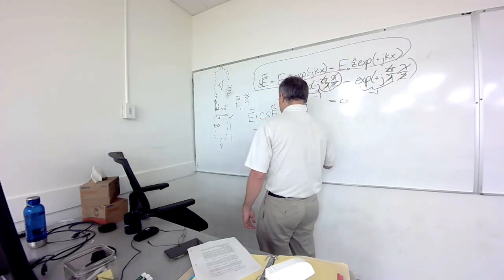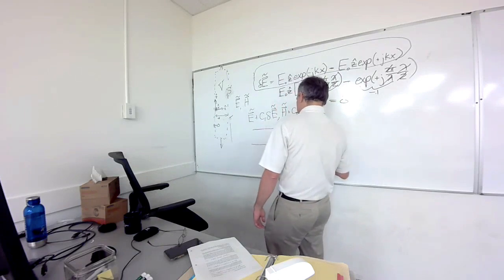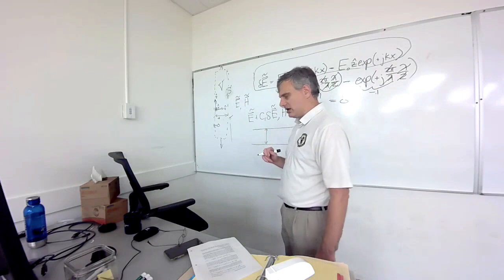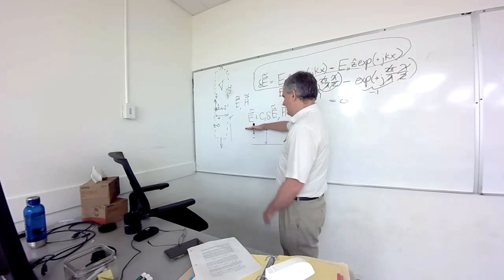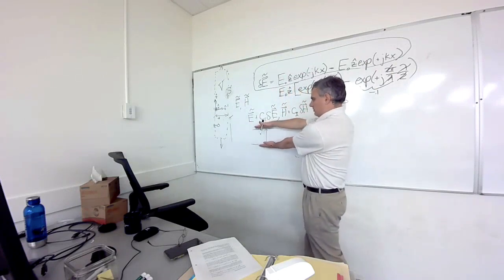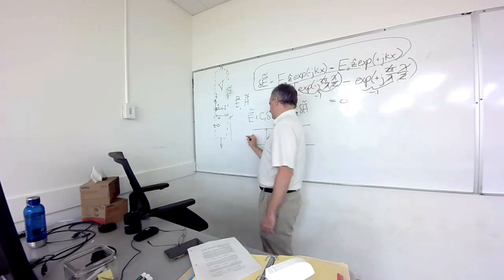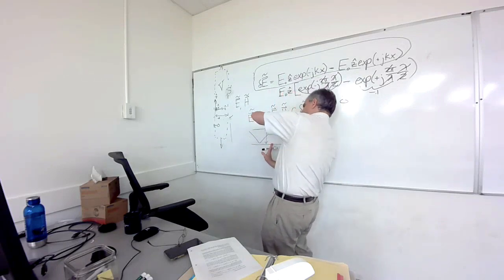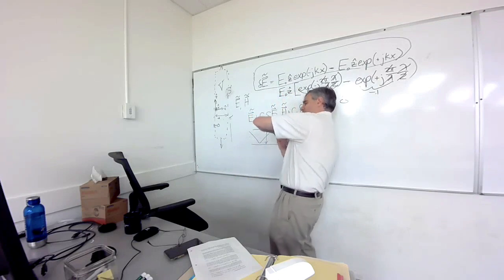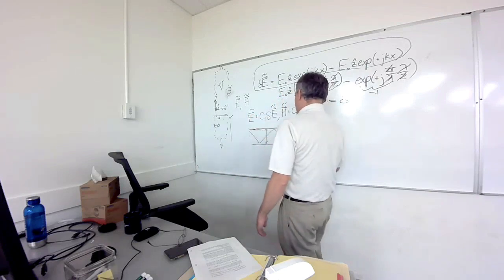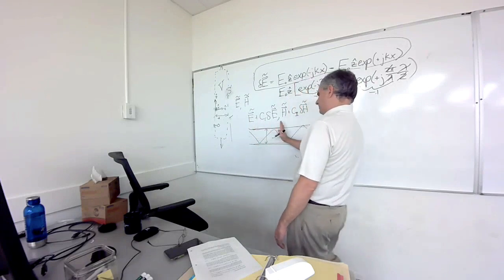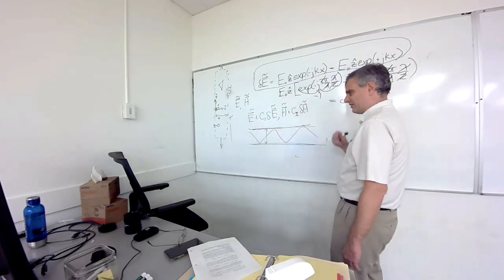So now I'm going to rotate everything by 90 degrees and say, okay, I've got some width here, but it's not in cutoff. If this were a metallic waveguide, if I had a metal sheet here, I could have a solution that basically represented two plane waves interfering with each other, putting zero field here, and propagating with a little bit of loss in the forward direction.